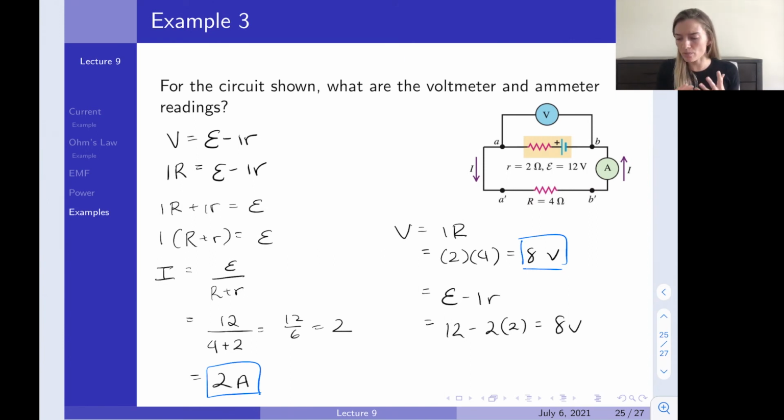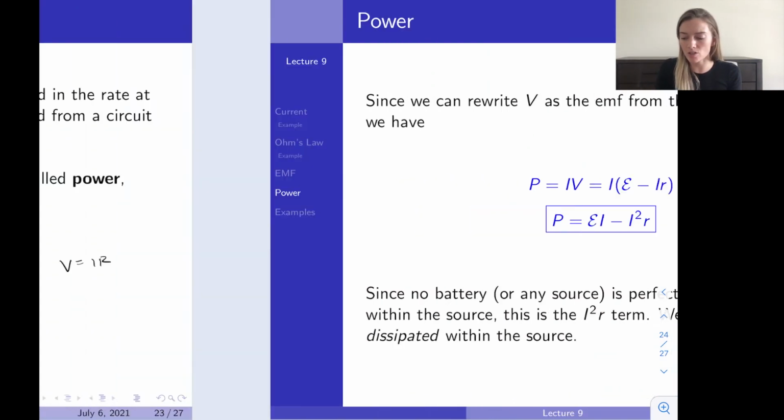And you might ask, how do you know if it's positive or negative, since I was a little careless with VA minus VB versus VB minus VA? Basically, it's because this is the positive terminal of your battery, the top of your potential hill. As soon as a particle goes past the positive terminal of the battery, it's been moved up to the top of that potential hill.